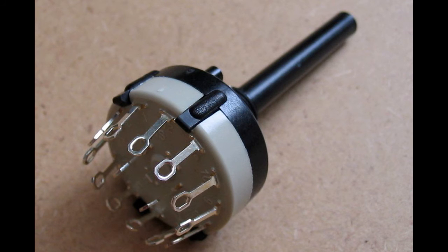Check this bad boy out. This is a rotary switch. So it looks like a variable resistor, but it's not. It actually connects that center pin to each of the outside legs, one at a time, as you rotate the actuator. That's fancy talk for the part that you grab onto and actually move around, the actuator of the switch. So you'll find that in premium microphone preamps, they will use rotary switches instead of variable resistors, and that's because of tolerance.